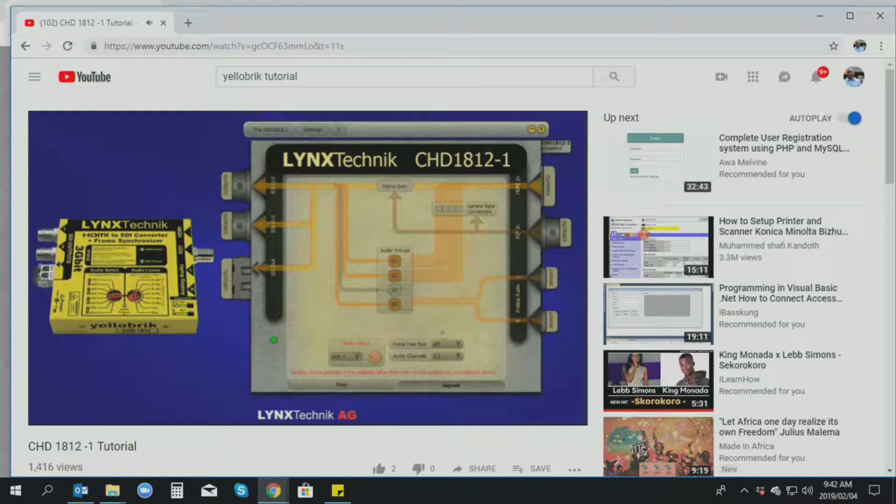Again, this is where you would change it, so I wanted to put it into AES1. You can see now I've routed the analog audio into 1 and 2, effectively overwriting them. Channels 1 and 2 from the HDMI are being ignored now, because I'm overwriting them with the analog audio input. And what you would do is select the channel that you want to inject that analog audio into, if you want to at all. A lot of the times you don't need to